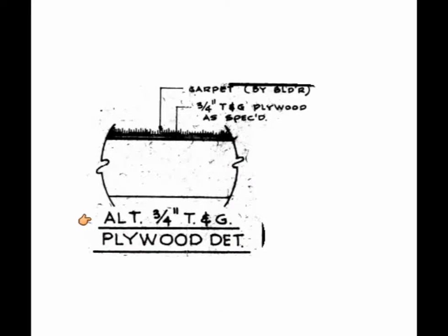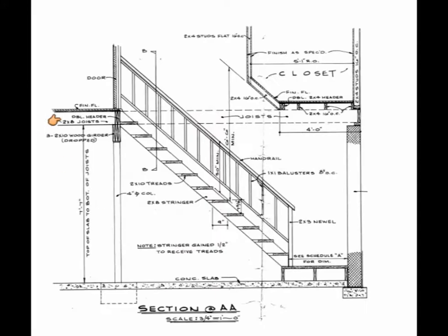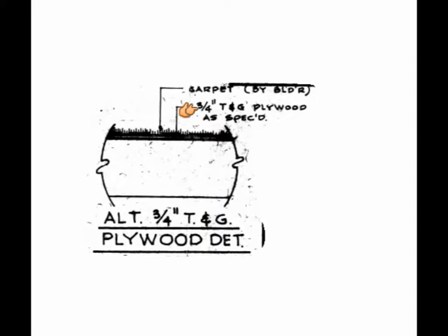Also on page 12 of your construction documents, you will see a detail view for the subfloor. This diagram informs you that the subfloor is 3/4 of an inch thick. This is why we named the floor object a 2x8 joist with 3/4 of an inch subfloor.